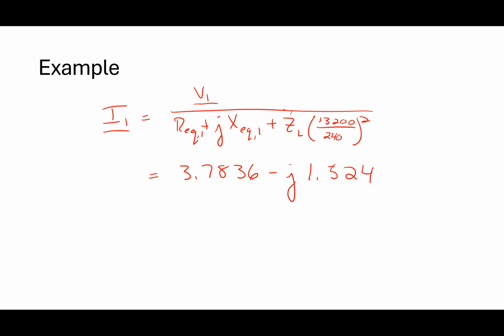How would I convert that to a per unit current? Sometimes I want to put that in per unit. Let's say I wanted to do that as I1 per unit. Basically divide by the base current to give me the percentage of the total that it is. We had found the I base primary, so on the primary side, the base current was 3.7879 amps.